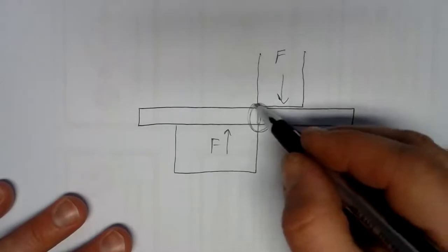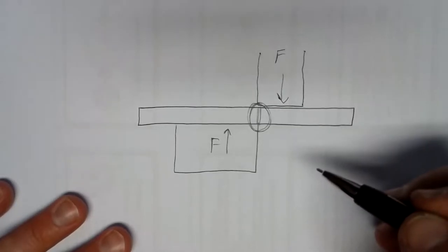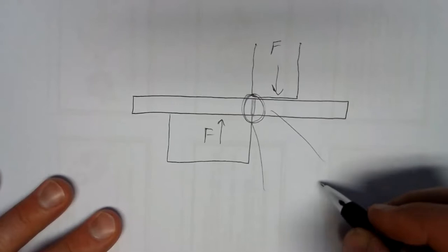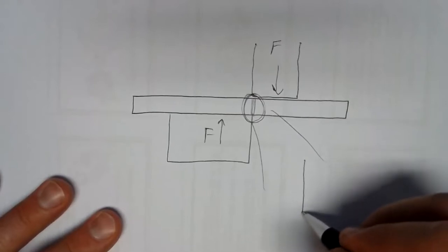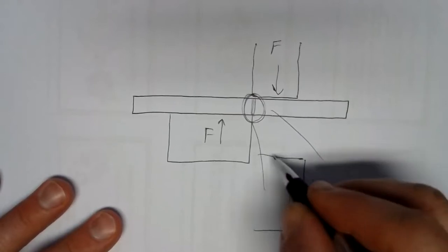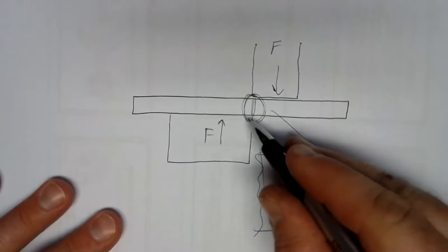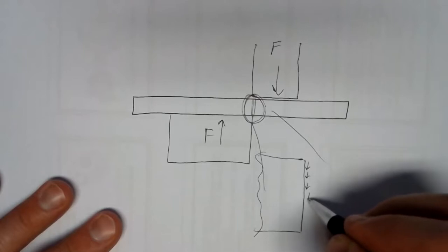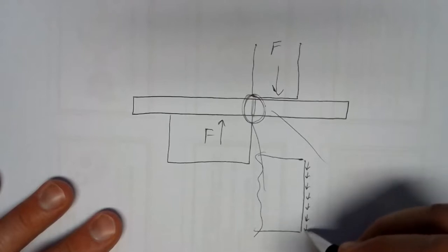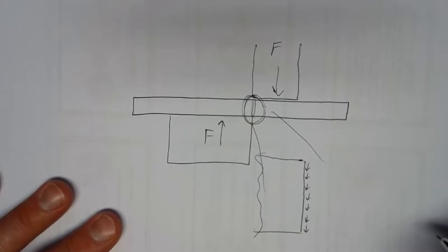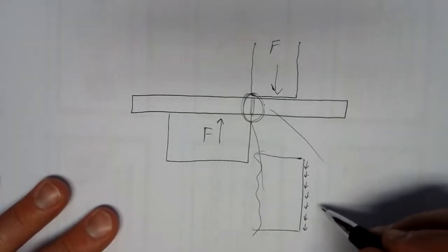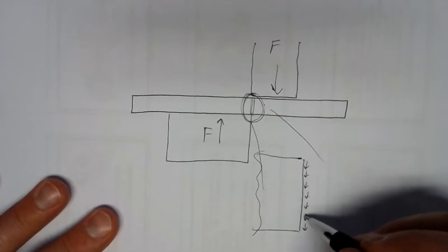Well, if we zoom in on this area right here, this area that we know is going to break when you push the sheet metal shear pedal down, what it looks like is we have this long area here. That's the sheet metal. So we got our broken line here. And the force is spread out over the area that way. Look at how that's different than the normal stress situation. In the normal stress situation, we were perpendicular to the area. Now the force is parallel to the area.